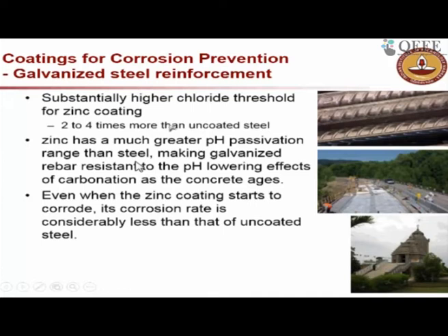Now one advantage of using the zinc is that you are increasing the chloride threshold of the steel rebar or the rebar system which has the zinc coating. The moment you put the zinc coating, now you need more chlorides for the rebar to start corroding.